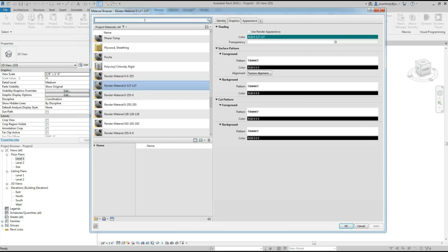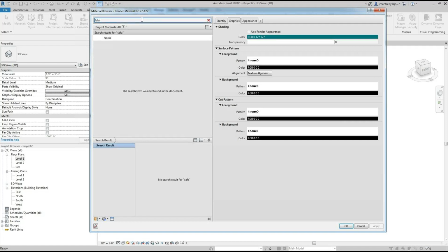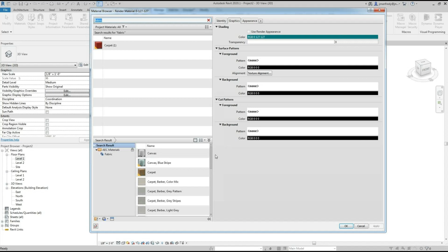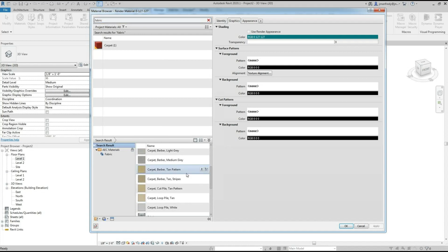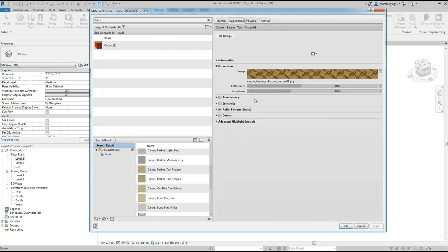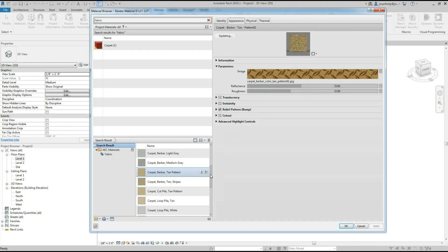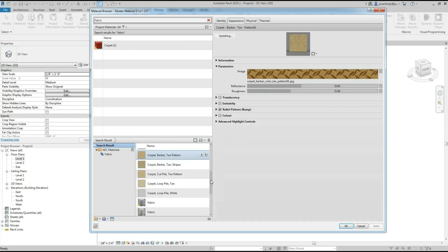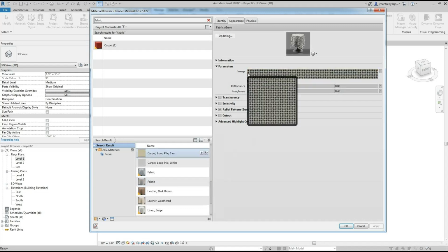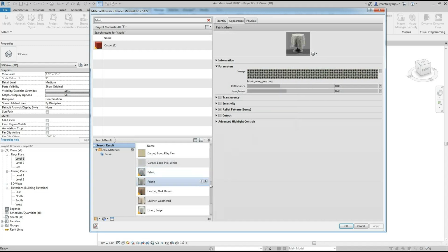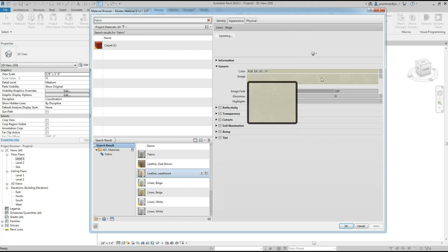And if I choose the material, as an example, I'll do a search for fabric. Here at the bottom are the materials installed on my computer. I'll simply choose some type of arbitrary material here that I can select and look at the pattern. Unfortunately, for imported models, the pattern that you typically want to use should be fairly simplistic. Ideally, just a color without a pattern here, because those don't correctly appear in Revit when you're dealing with renderings. This would be like a solid color, for example.